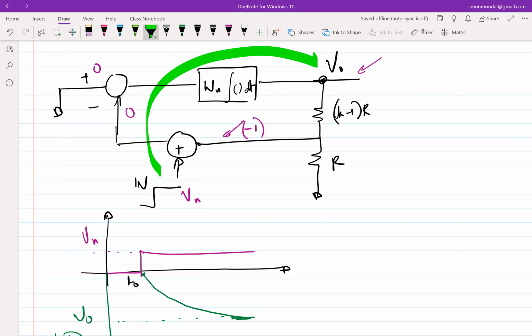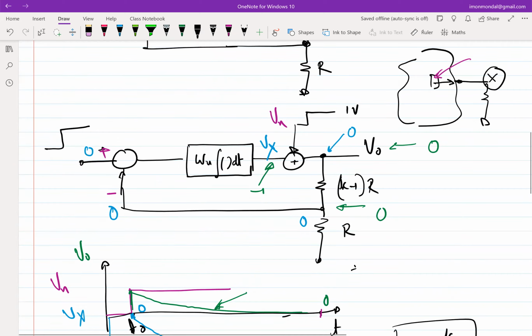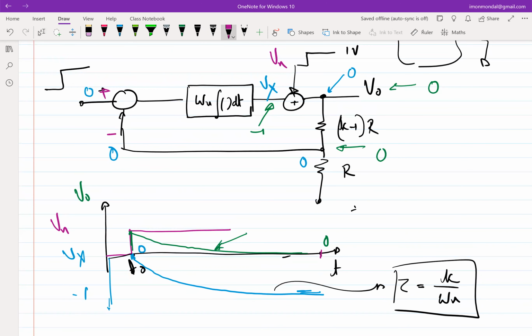So that's the more mathematical way of going about doing your things, right? Thank you for pointing that out. So what I want you to do is to figure out the transfer function between these points, right? Figure out the transfer function when you apply an input here to here, or when I apply an input to the final output. So find out V0 over Vi when Vi is located at different points of the loop.